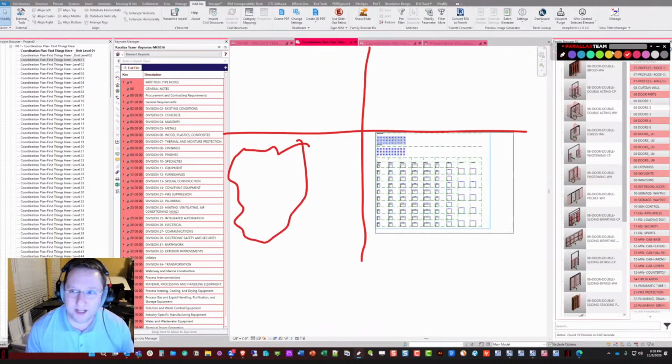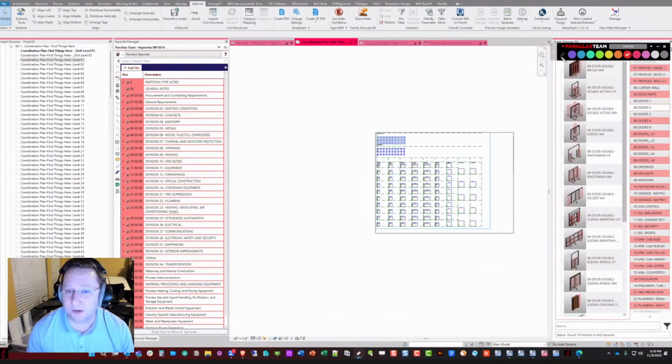So it's way below, but the entire project is also nowhere in the XY plane near where the units are. It's out of sight, out of mind. Also, there's a different level for sea level and for the two units. So should you be near sea level and want to cut a section through it, you could always grab the two unit levels and shove them another 1,000 feet down, and nothing would break.